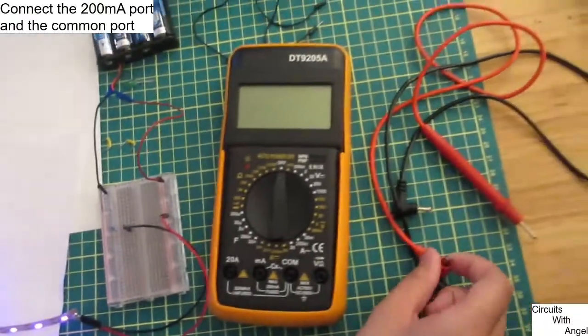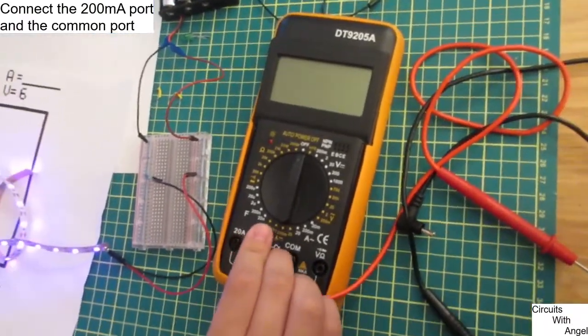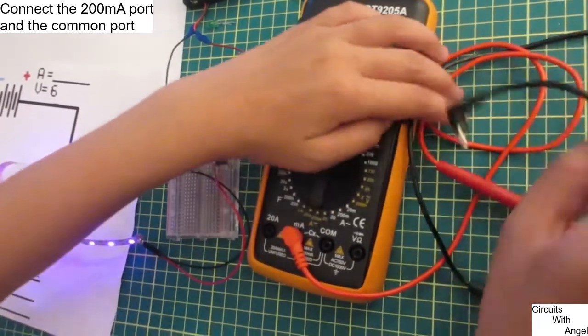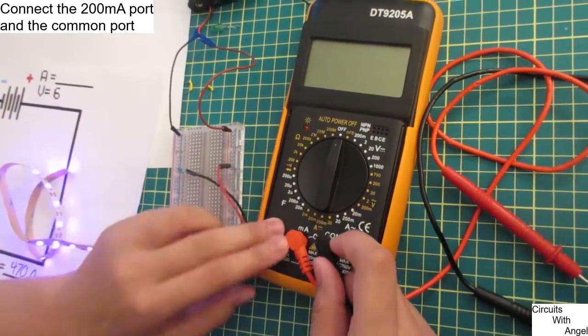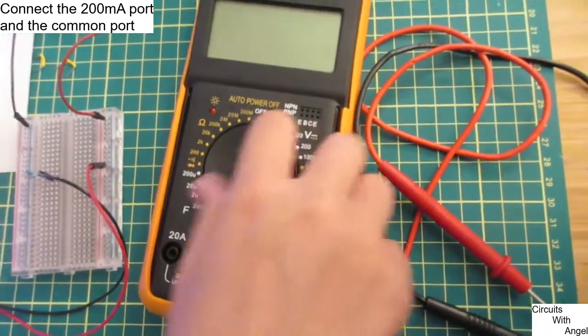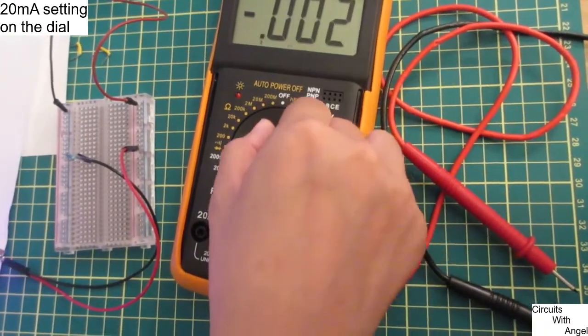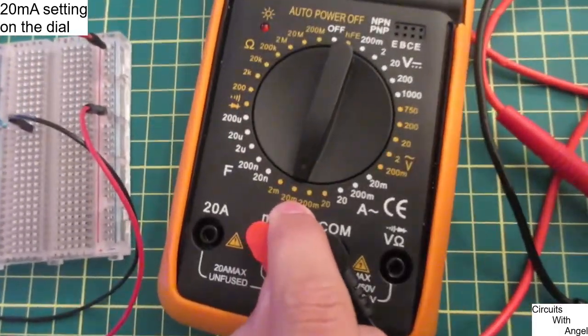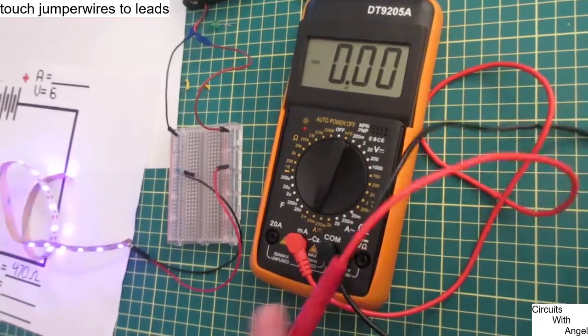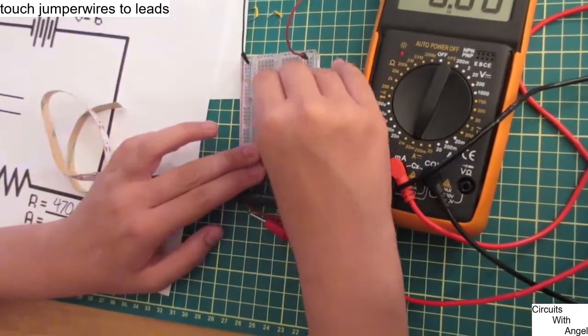Alright, now we gotta measure our current so we can find out the voltage. I unplugged my ports so we can do it again, just so you know how to plug it in. So we plug in our ports to 200 milliamps and common. By the way, if your multimeter isn't working, make sure your leads are pressed down into the port. You can't just have it on top of it, or else it won't make a proper connection.